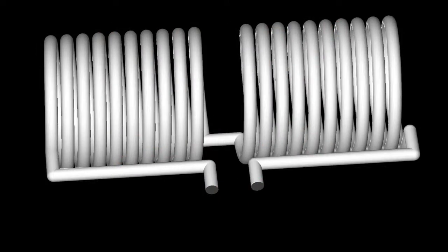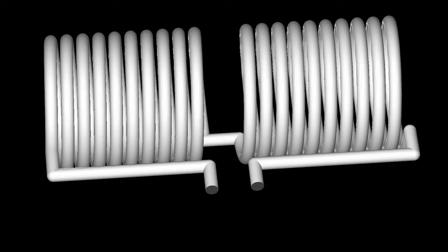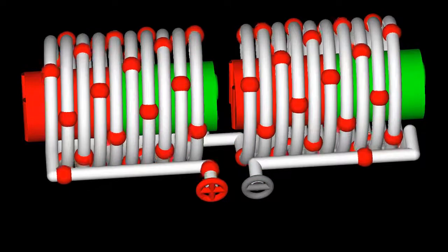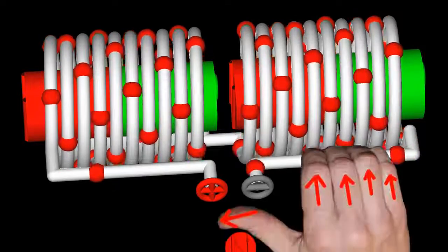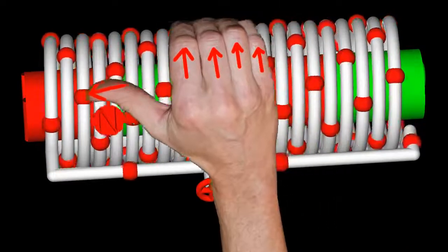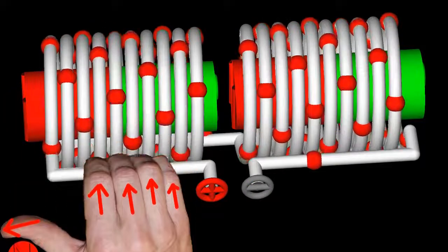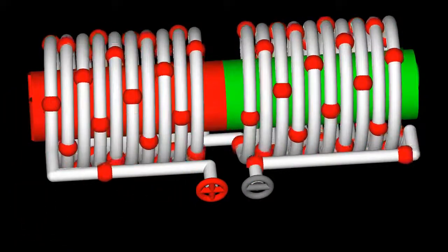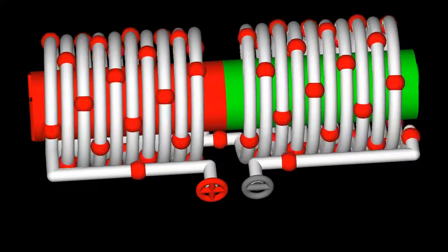With an alternating magnetic field of a solenoid, we will now try to produce rotational movement. There must be a gap for the pivot axis at the center of the solenoid. If a current flows through the wire, both halves of the solenoid can be treated as a single electromagnet. Each half's magnetism will be in the same direction as the windings. The magnetic north pole is at the left, thus the south pole at the right end of each electromagnet. The magnetic field of the arrangement differs just slightly from that of a single electromagnet.